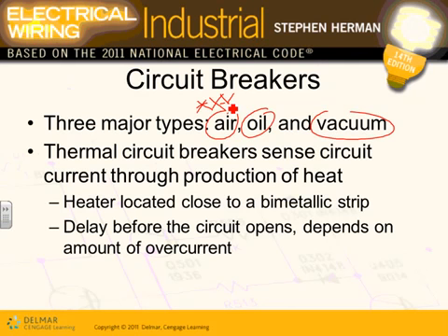Now what the heck is oil? The oil circuit breaker, guys, what they do is they put the contacts, they immerse them in oil. When they open, it extinguishes the arc. That's an oil circuit breaker. They use it in utilities, Adam, in high voltage. An oil circuit breaker is a tank full of oil. You're going to see in a second. They open everything in the oil.